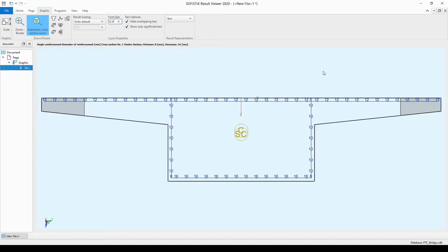Maybe the best is to illustrate it in the cross-section view. So the height of the tensile zone is 240 mm, which is roughly about here. And in this picture I am presenting the diameter of the rebars. So as you can see, diameter 10, 8 and 16 bars will be involved in the analysis of this D value according to a weighted procedure.